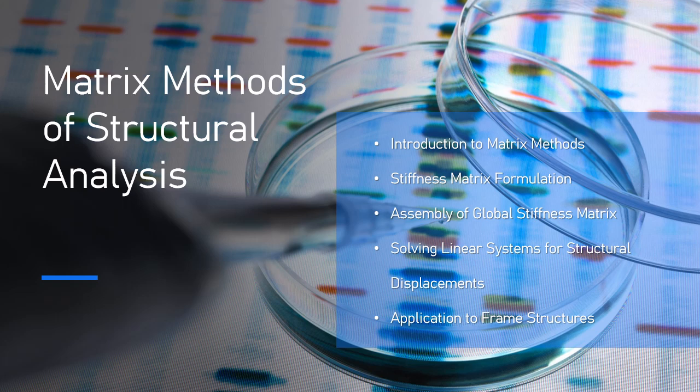The application of matrix methods to frame structures involves using the global stiffness matrix to solve for the displacements and internal forces, bending moments, shear forces, and axial forces in each element of the frame.